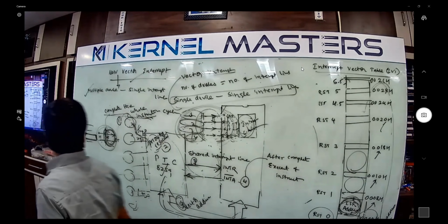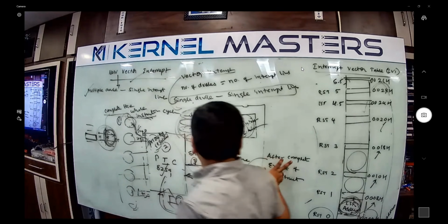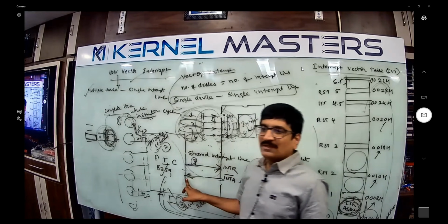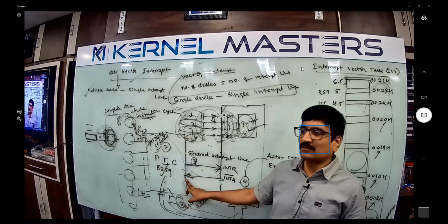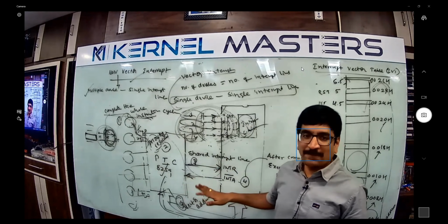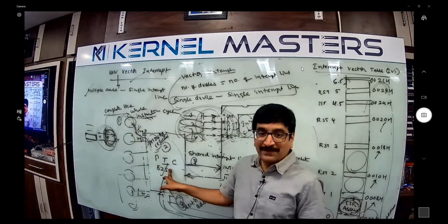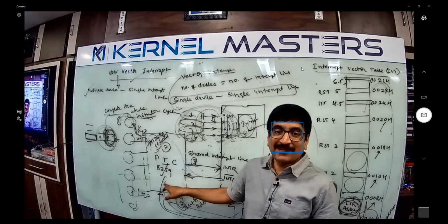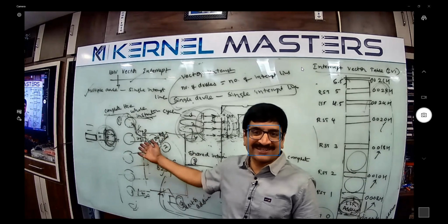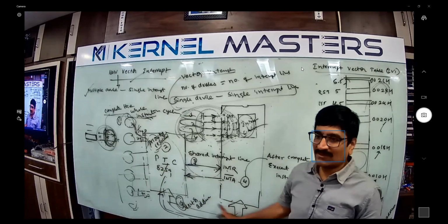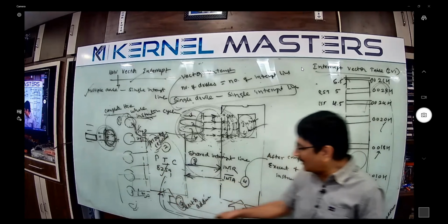After complete execution of the instruction cycle, it can send the interrupt acknowledgement signal. The acknowledgement signal indicates the microprocessor is ready to handle it, but the microprocessor doesn't know where to go. Whenever the acknowledgement comes, the PIC understands. The microprocessor understood, but it doesn't know which interrupt occurred, only the address. Then it immediately sends the address on the data bus. Once the microprocessor receives the address, now it can go.